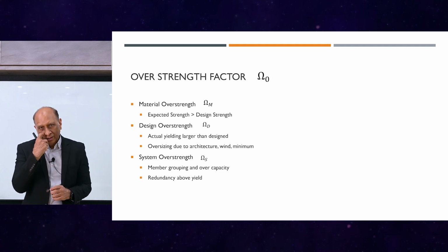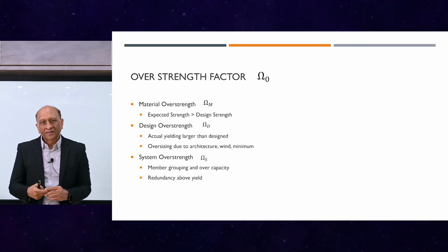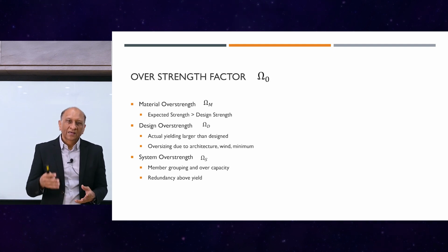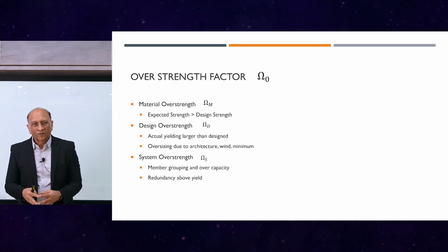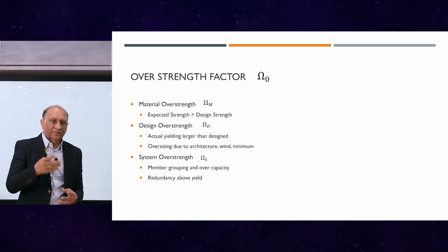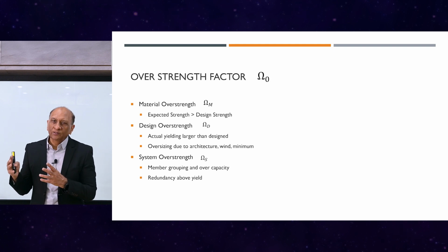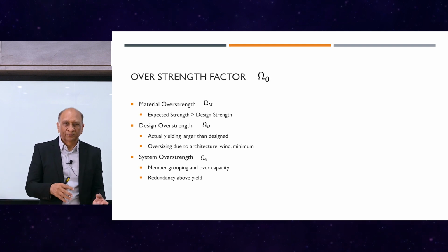But the reality is that the column is not just gross concrete. It has reinforcement, it has confinement, it has spacing. So this is the typical detail of that column. We generated that from ETABS detailing, and you look at that, there's a lot of things going on. So we need to incorporate that into the capacity.